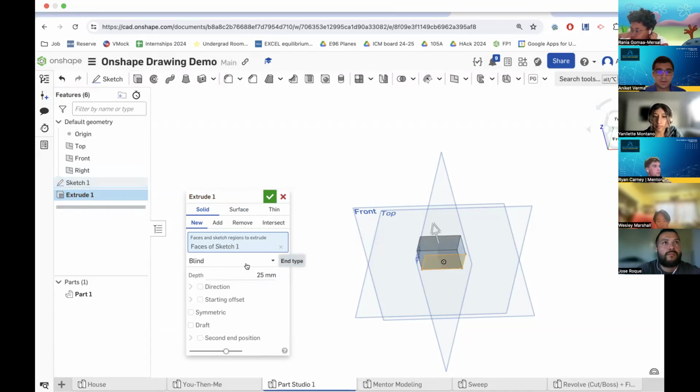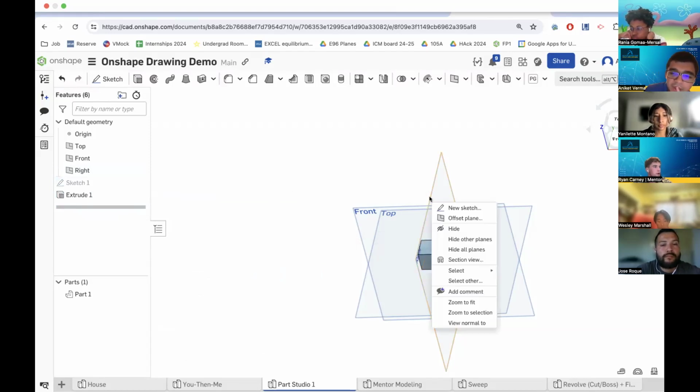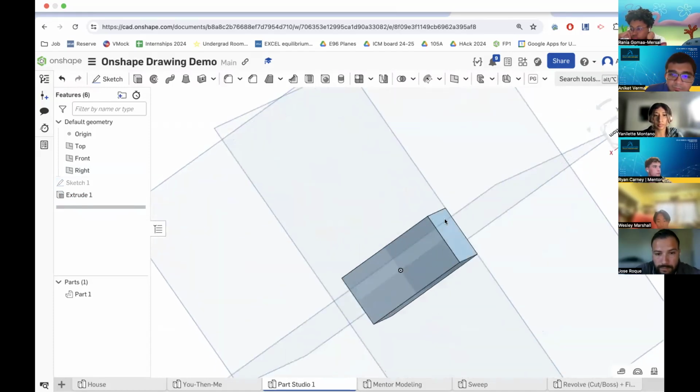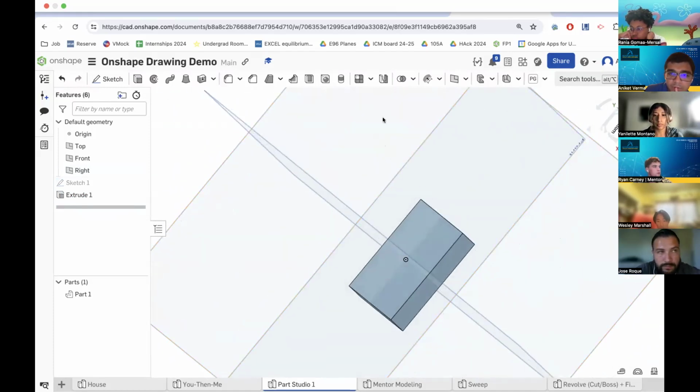And then, changing no settings, I can just make the depth of this extrusion 20 millimeters, because that's what we want to do the extrusion as. And once I hit OK, I'll have a 3D rectangular prism. Cool. Questions? No questions?